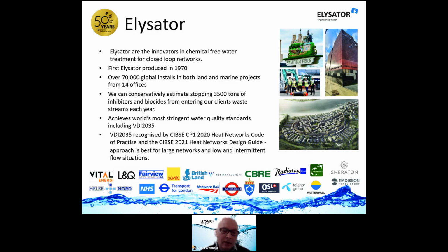We achieve the world's most stringent water quality standards, including VDI, which is the one most prevalent in manufacturers' guidance documents. Last year, VDI was recognised in the CIBSE Heat Network Code of Practice. There's Table 17 in there, which gives you the full VDI parameters. And in the heat network design guide, CIBSE actually state that the DMIN approach is the best for large networks and for networks with low and intermittent flow